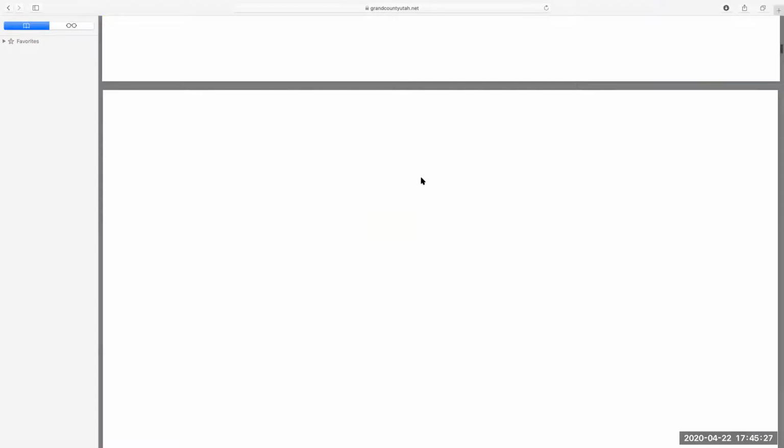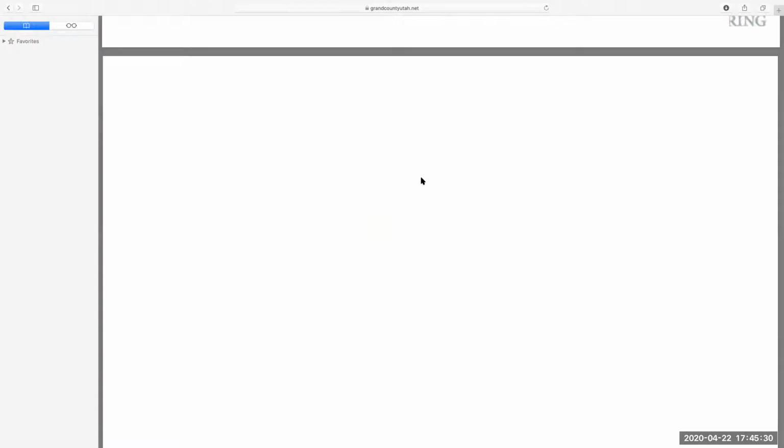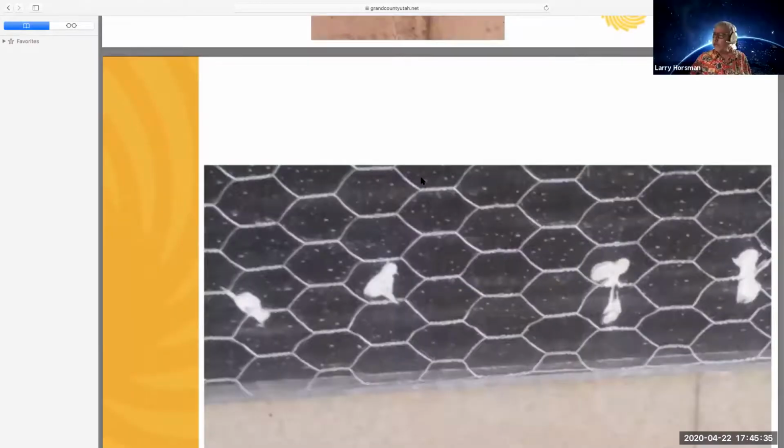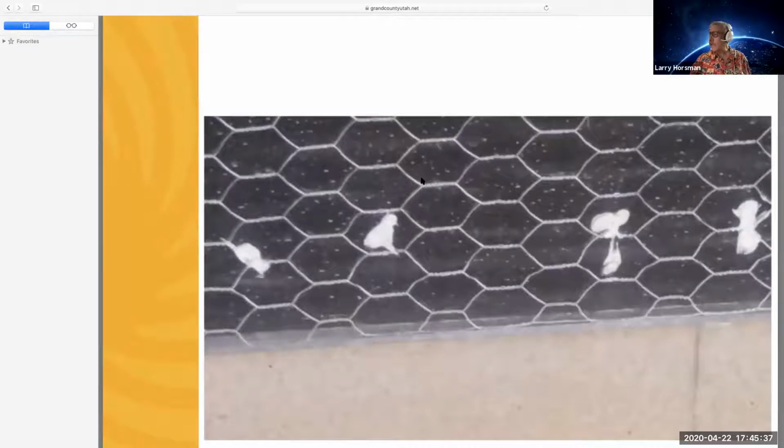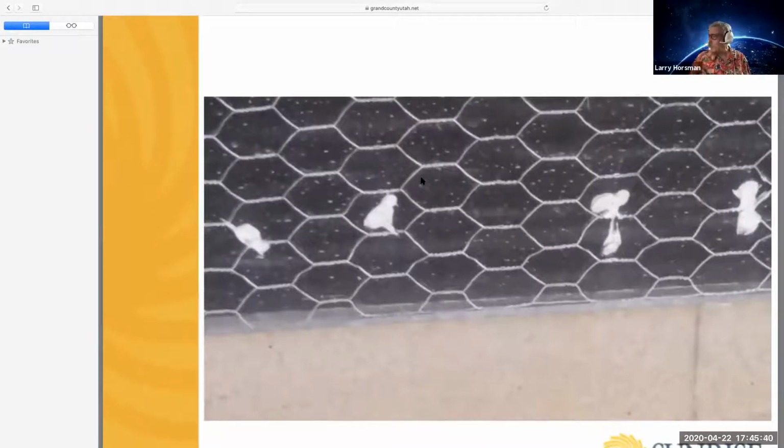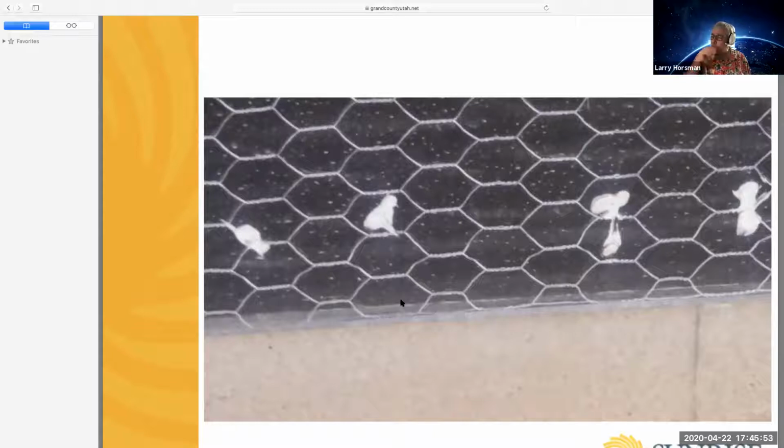Is there a difference, Larry, with moisture stop when you're doing siding and stucco? Yeah, they have wood stucco stops or molds. There are also some slightly different ways to terminate this. You see, this isn't terminating in a screed per se. They've got some other type of system. The problem is, in this you'd have to have some holes in the bottom because you don't want to trap water behind the stucco.